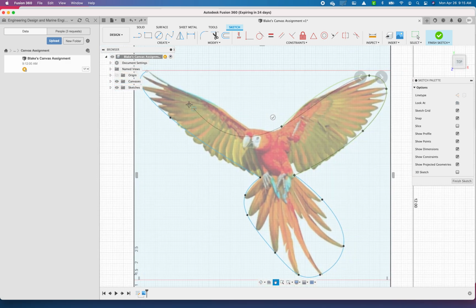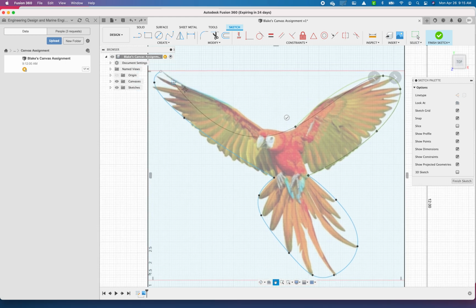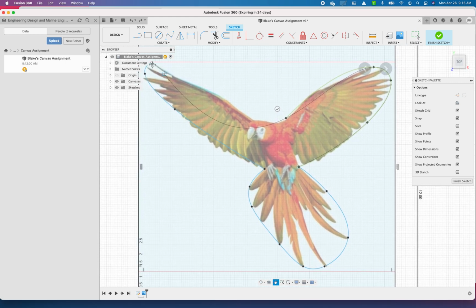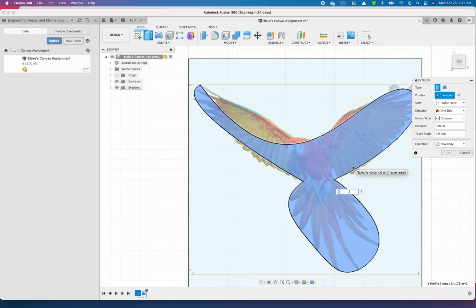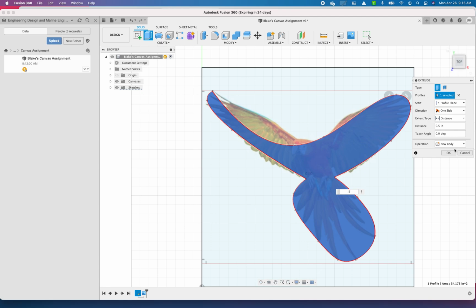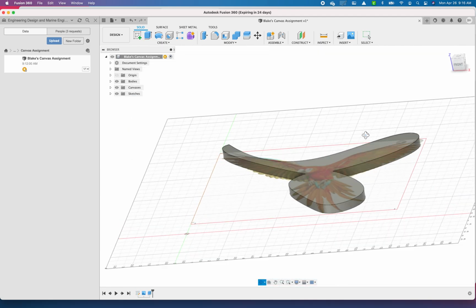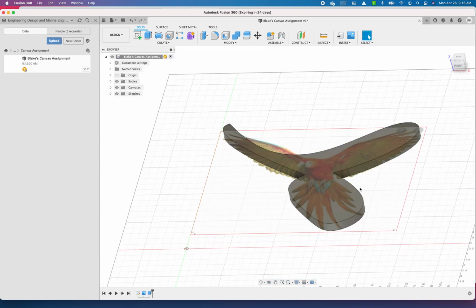But a very rough job would look like this. Something like this. And then I would extrude this shape 0.5 inches like this. And this is complete. Alright, obviously we should do a better job than that, but I wanted to give you an example, and go ahead and try that out, and save it into this folder right here.